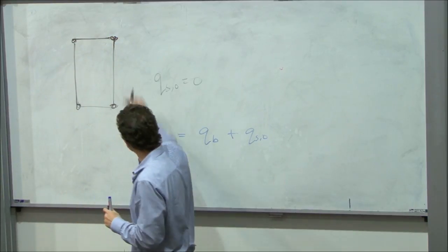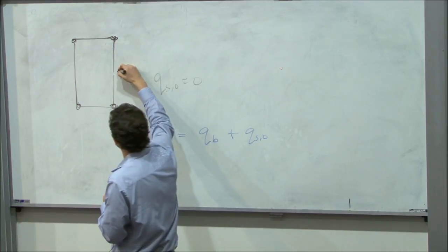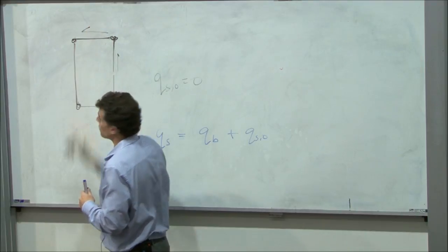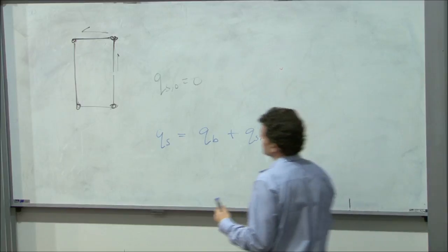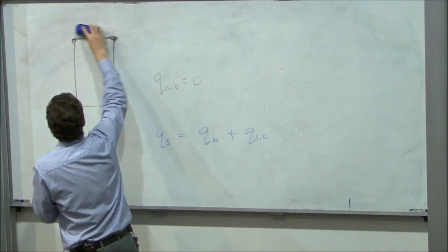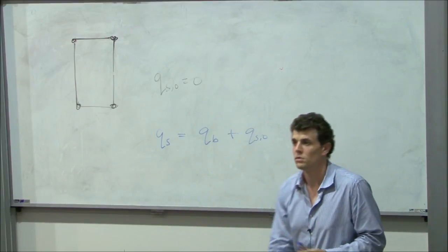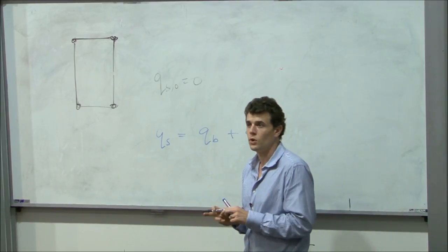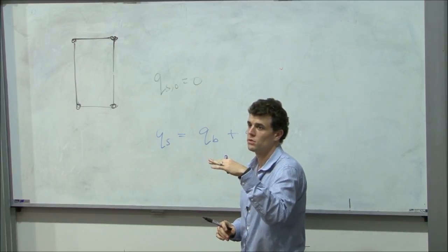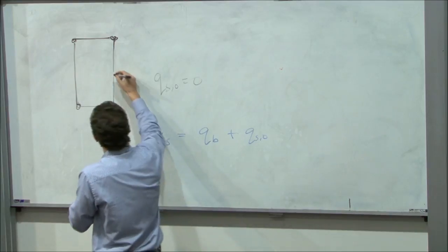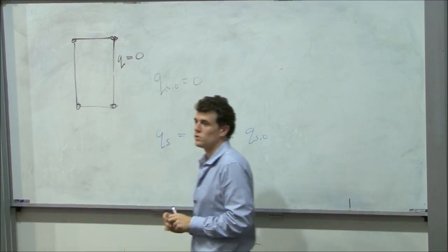Last week, if we had a box, we would have made a virtual cut on the edge of the box and worked out the shear flow as we went around the loop. Now, the benefit of our idealised calculation is that once you make a cut in the panel, what happens to the shear flow in the entire panel? Well, the shear flow in the entire panel is constant. So if we make one point 0, the whole section goes to 0. So when we make our cut, Q in that panel goes to 0.